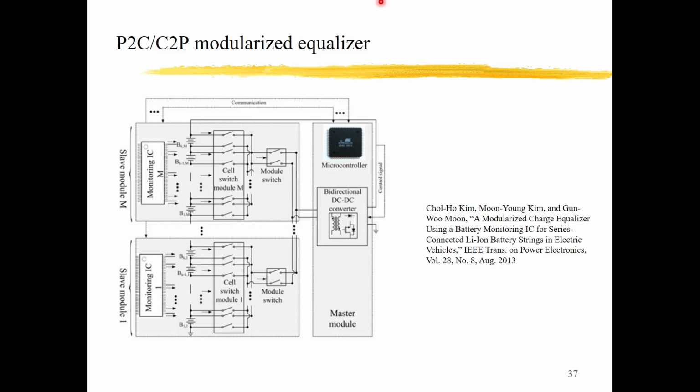the power required by the EV is getting higher. When the power is higher, we have two methods. One, either we increase the current, or we increase the voltage. Of course, we prefer higher voltage, because higher current means higher loss.